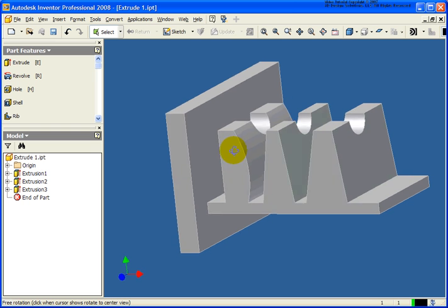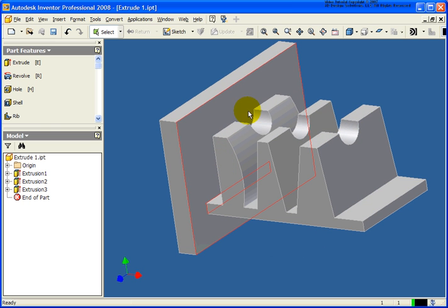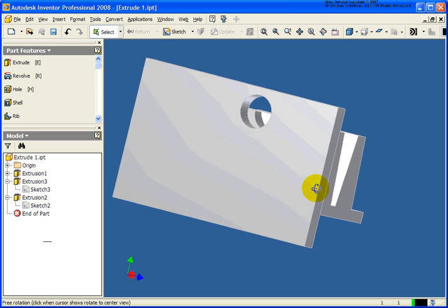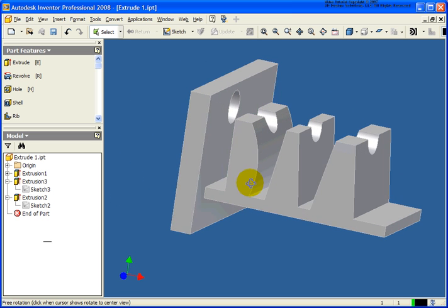And you'll notice what happened is the cut did not go through that front face, because when I did the All operation, that was with extrusion 2, it does not know that extrusion 3 exists. So that's why I had to go back and replace that. I can go back and just reorder it just by dragging extrusion 2 below extrusion 3, and it now goes all the way through the parts. So that's also referred to as feature reordering.